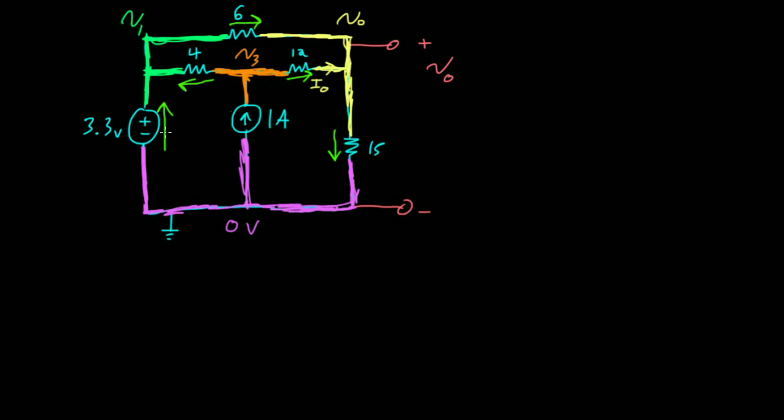One note on this, I'm just guessing about this. There's absolutely no right answer, no wrong answer. I could reverse the direction of all of these. I could reverse the direction of some of them. It completely doesn't matter. It's going to change the way I write the equations, but if I want, like here, just for the sake of argument, I'm going to reverse the direction on my 4 ohm resistor, just to show you that it completely doesn't matter. I can absolutely reverse this current direction and I'll still get the correct answer for this circuit.